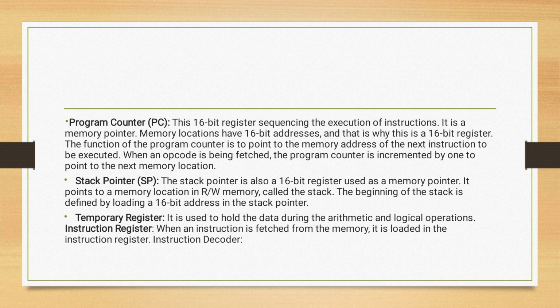Next, stack pointer. Stack, which I have already discussed, is a kind of storage container from where we can retrieve or store data from a particular register into arbitrary address locations. This is also a 16-bit register used as a memory pointer, and a particular technique is used in a stack. This is called the LIFO technique, last in first out. The beginning of the stack is defined by loading a 16-bit address in the stack pointer.